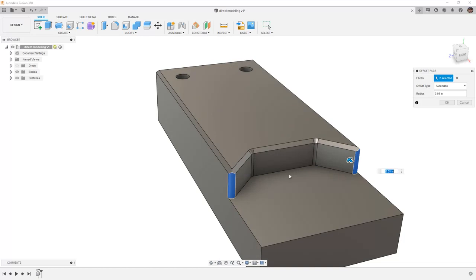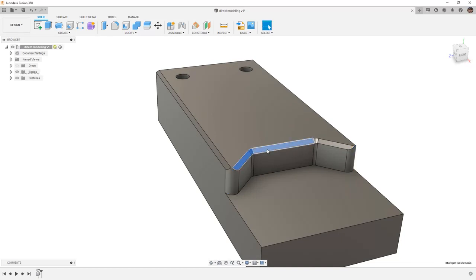Another option we have is to use other tools such as extrudes. We could simply extrude a new top edge and include that fillet if we need it. Once we say OK, I can go back around and I can reselect some of these chamfers. And note, because they no longer continuously go around the body, I can hit delete as soon as I've selected one of the closed areas.